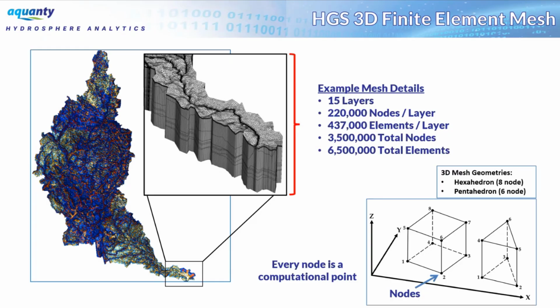And the simple fact is that HydroGeoSphere is based almost entirely on highly nonlinear governing equations. So three-dimensional form of Richards' equation. This is much more complex than Darcy's law. So the model runtimes for HydroGeoSphere are something that all users will kind of struggle with. That's par for the course with a model of this complexity. And so the advice is always to try and bring an austerity mindset into your projects. Really try to work with as few nodes as possible, because that's going to save you a lot of time down the road when you need to run this model a couple dozen times for calibration purposes or to run different case studies.